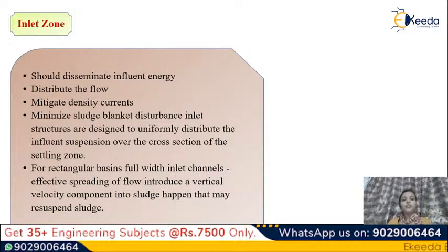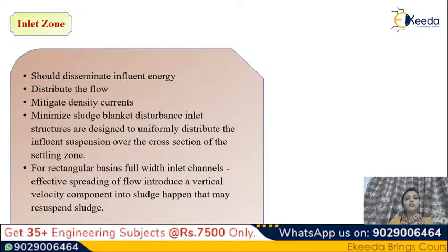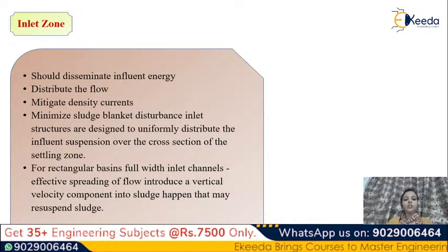For rectangular basins, full width inlet channels give effective spreading of flow, but they introduce a vertical velocity component into the sludge zone that may resuspend sludge.